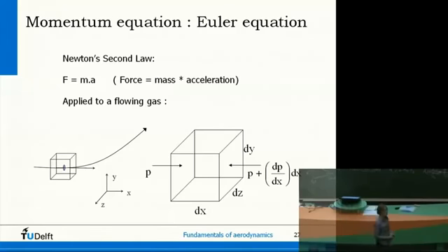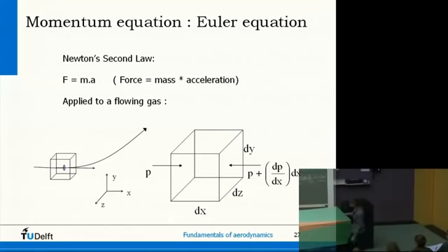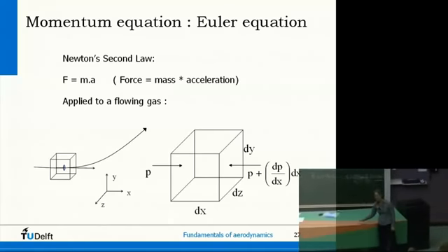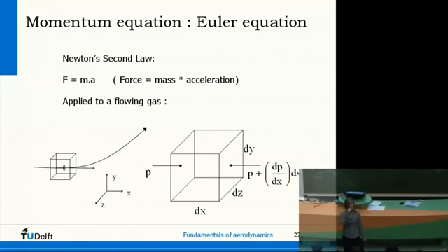Any other forces we might need to neglect? Tau w, frictional forces. Perfect. In a real flow, of course, we have friction. So if we have flow over an object, and the flow attaches to the object, and we have fast flow on top, due to frictional forces, it's only friction that can make this change of speed in the flow. However, this friction, for our applications, high speed over wings, is only relevant inside the boundary layer. And that's a very thin layer typically. I will show you later how you can compute how thick it is. Thin layer, and throughout this layer the pressure is constant. So the pressure doesn't change much. So I indeed neglect friction.